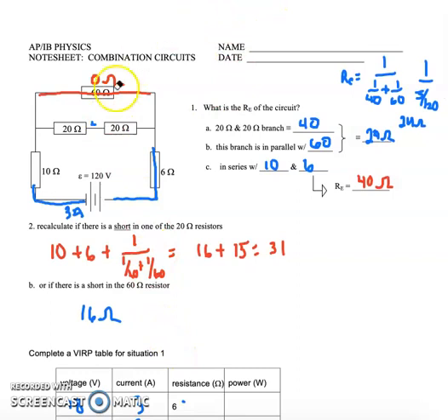So what I want to look at is their relative... there's a number of approaches I can do here. In fact, I'm going to see if this approach makes sense. If I just figured out I have a 30 volt drop here and an 18 volt drop here, then by the loop rule, this is 120 volts, the drop for any loop has to be 120.